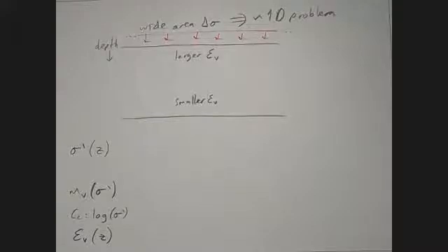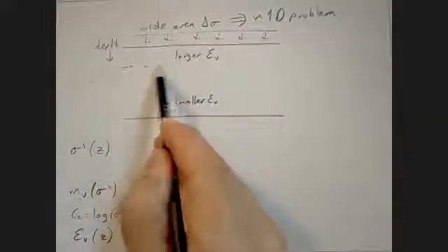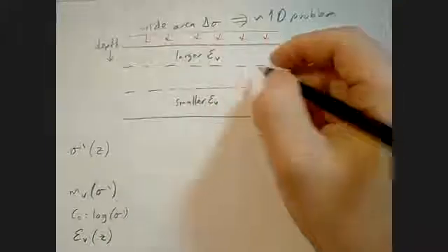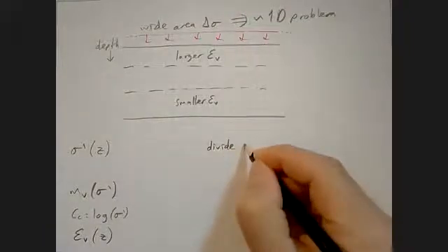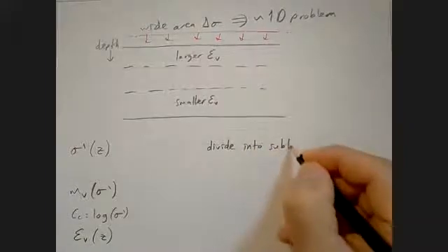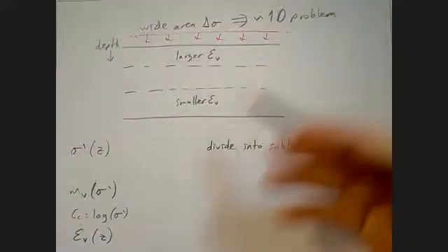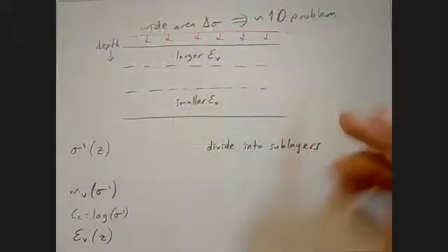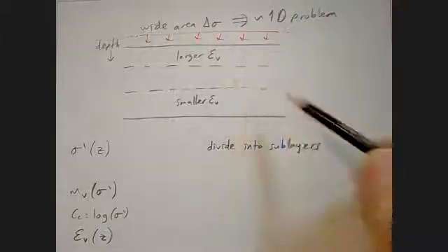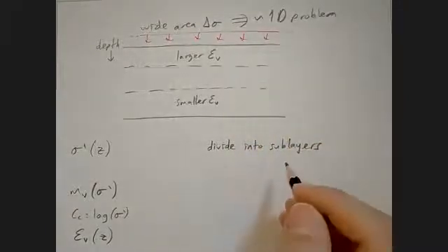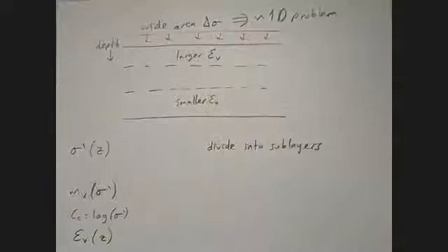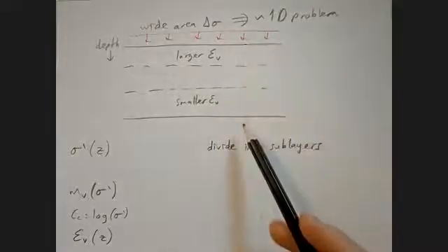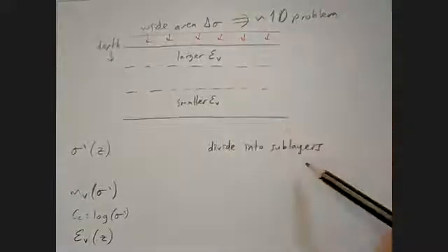So the way we address this is we divide it into sublayers. If you are doing this by hand, you can divide it into like 2 or 3 sublayers, usually maybe 5 meter layers or something like that. But in our age, you have spreadsheets, so you can actually divide it into like 1 meter pieces or even 10 centimeter pieces if you like, because they will all use the same equation. The difference is going to be the stress levels. And then once you divide them into sublayers,